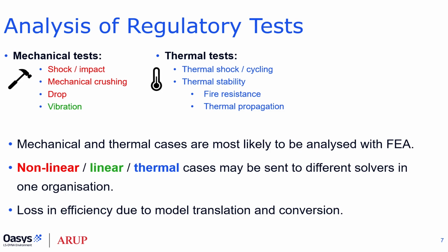So let's look at the tests that are most likely to be analysed with finite elements. These are likely to be the mechanical tests and the thermal tests. You can see from the list of mechanical tests that there are some that are similar to crash cases that we would solve in LS-DYNA, such as impact and crushing. But some of the cases like vibration might be analysed by a different department in an organisation, for example the NVH or durability department, and they might use a different solver. And the same is true for the thermal analysis. This might be carried out by a different department, say the powertrain team, and they might use a different solver.